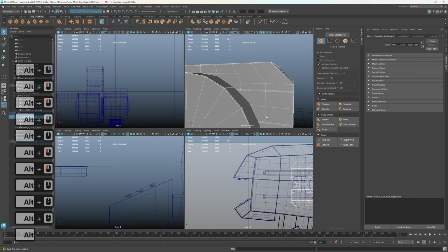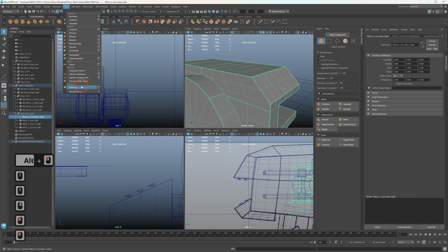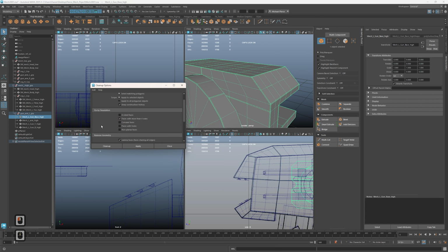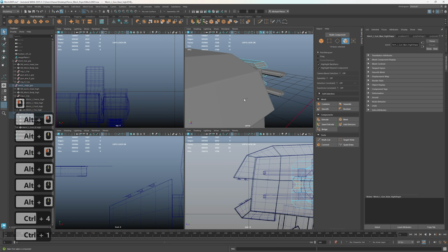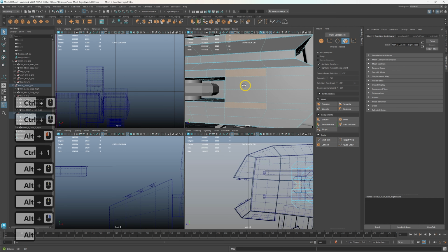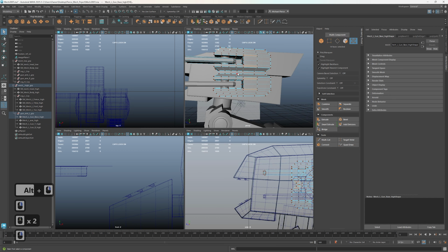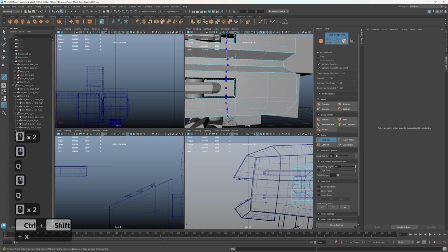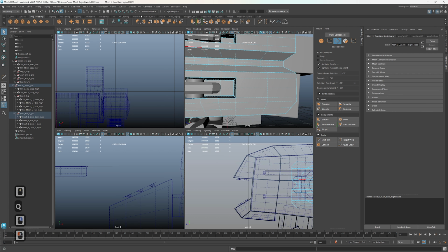Pretty sure my only real concern would be, well, actually, I can actually see what I have. Mesh. I'm going to do this really quick. Make sure I have that. More than 4 sides, lamina and non-manifold. Hit cleanup. Well, let us first. Object. I'm going to put a cut down the center here. I'm going to grab this line and symmetry with topology.